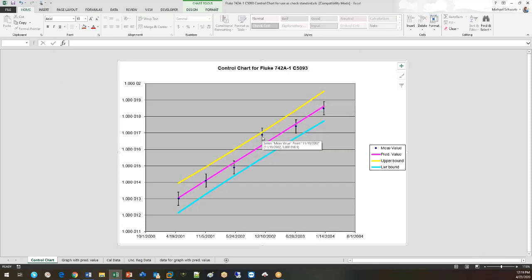This is Brian. This is the control limit. It's called control limit. It's a trend chart. Yes, so control limits define that. Are they using this to determine the pass-fail of the resistor as found for the calibration? Because I'm also seeing the uncertainty bars around the chart for the measured value. Yeah, that's incorrect. It's the uncertainty of the projected value. Is that what we're seeing as the upper and lower bound? It's from the standard deviation, and should be 2 sigma or 3 sigma.